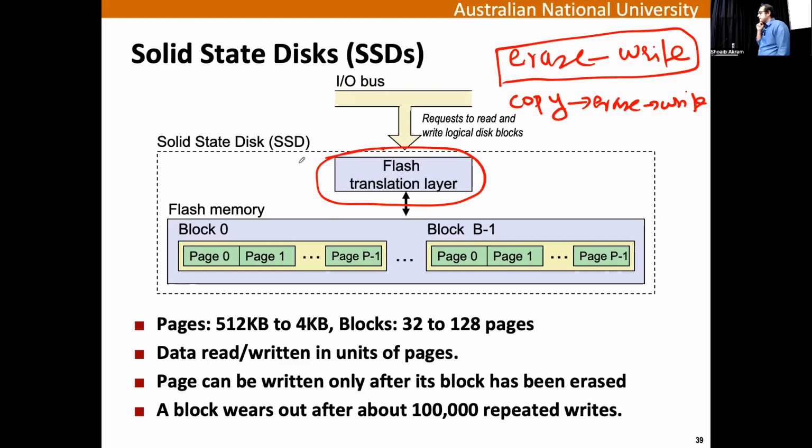The other thing it does is something smart to minimize the number of erasures, so you don't have to erase so much. There are a lot of techniques today that flash translation layers use to minimize the number of times you have to erase a block. We won't get into that. But basically, every time you have a write, you can do something special. You can remap that page to an already erased block, stuff like that.